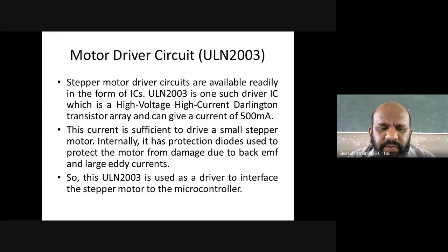And so that is why we are going to use this ULN2003 as a driver circuit or an interface between your stepper motor and the microcontroller or microprocessor, right? At some point of time, you might find the word microcontroller used, no issues. Your 8051 or 8085 or 8086, anything for that matter, you are going to use an interfacing circuit, and that has a driver circuit, in this case ULN2003.